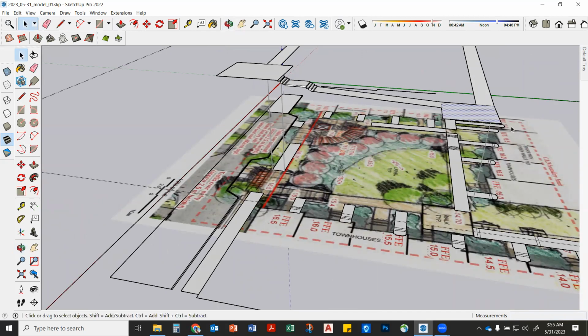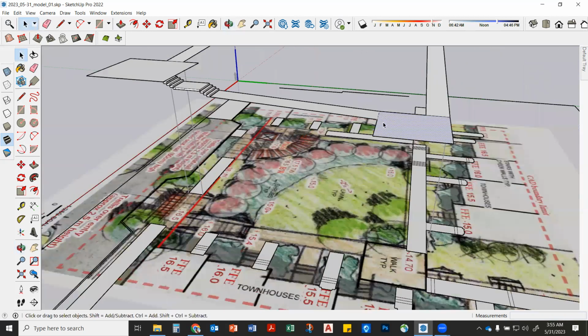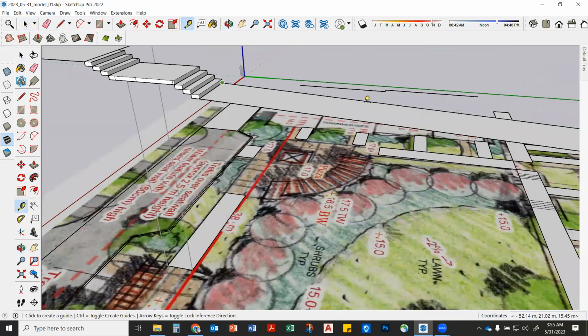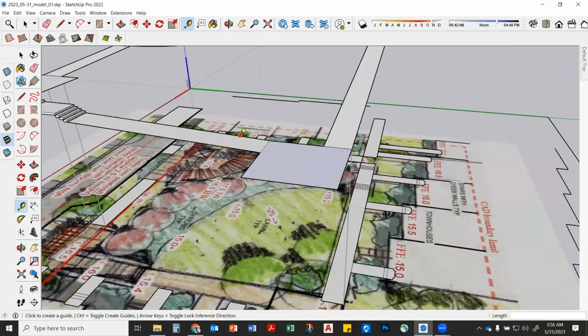Rise over run. Yeah. So you can just use the tape measure. But remember, when you're measuring that, you don't want to measure along the length like this, yeah? That'll be incorrect. You want to go straight out like that. You come to here, and you can figure out what that is, yeah? Do that for the other one too. When I designed it in imperial units, I had it underneath 5% because you don't want to ramp. So let me know if I'm correct, yeah? On both of those. Because if I'm not correct, it's over 5%.